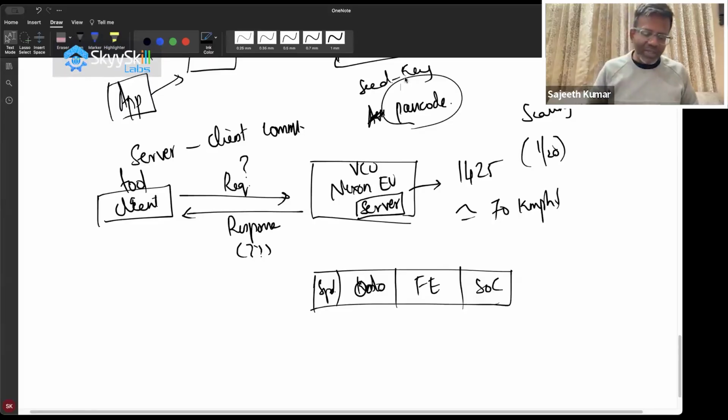So what this means is you cannot expect to buy a Tata Nexon, connect a CAN device to it and allow your students to monitor the CAN messages. You will not be able to do that. Why? First, there is a seed key which we'll need to crack. Or for all I know, maybe they've already implemented encryptions. I'm not sure about it.